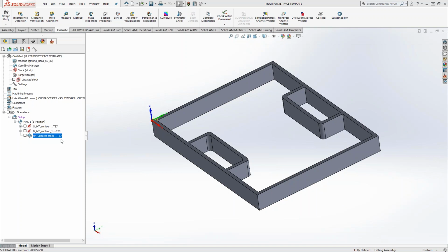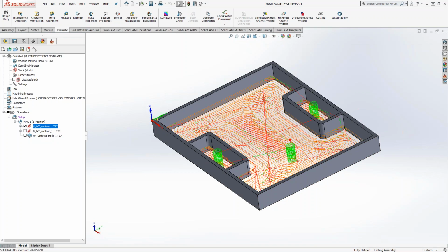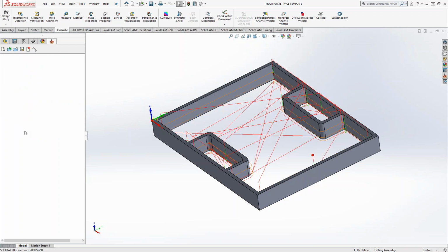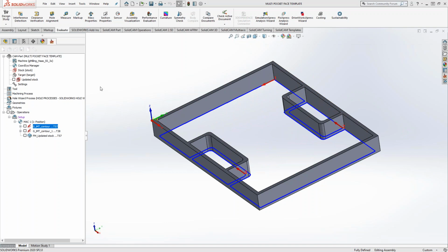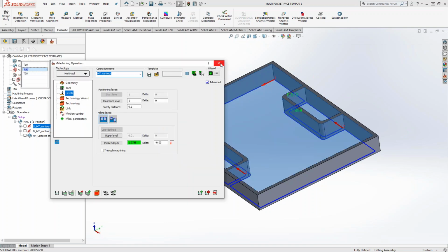So let's take a look at what I did here. I have a 2D iMachining for the inside pockets using a 1-inch tool, I believe, and then a half-inch tool doing a rest operation. Now, in modern SolidCAM, it's basically one toolpath with the multi-tool option engaged. If we take a look at that real quick here, I have the 2 tools here. So there are 2 toolpaths in the list, but it's one toolpath with the 2 tools selected. So in this case, I would be able to just save one template, and it would save all those tools.